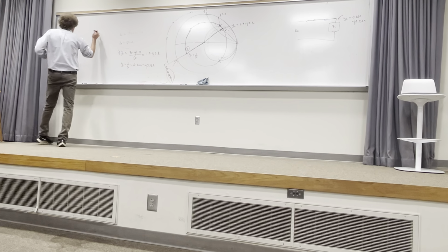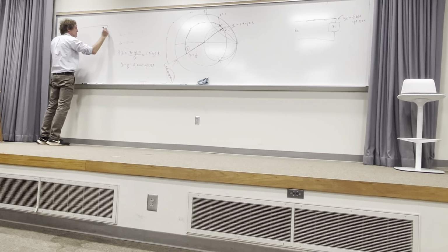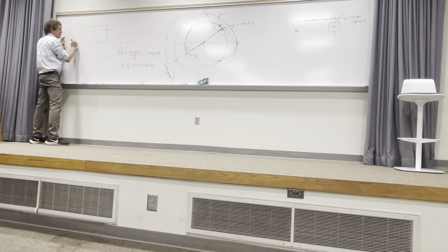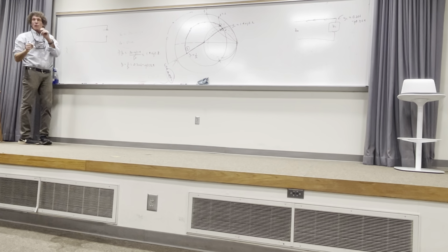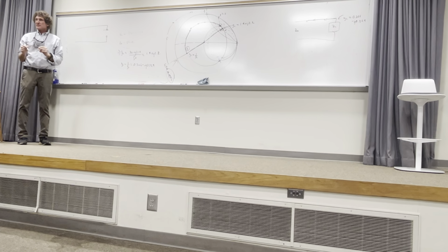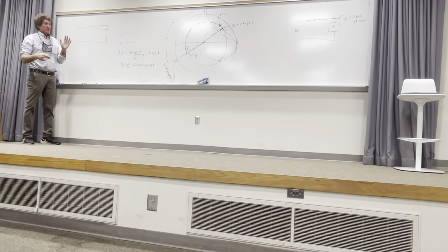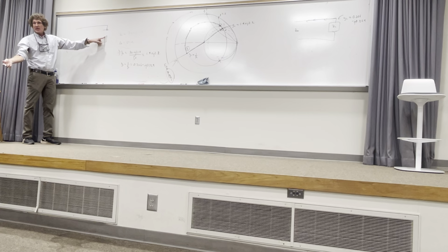So now for the stub itself, it's going to be an open circuit stub, right? Now we're going to work in the admittance domain. Please, you all follow me. Anytime we're in parallel, we're in the admittance domain. So I go through this the same way I always do. I start with the load impedance, which is infinite, right? If it's open circuit, there's no load, it's infinite.